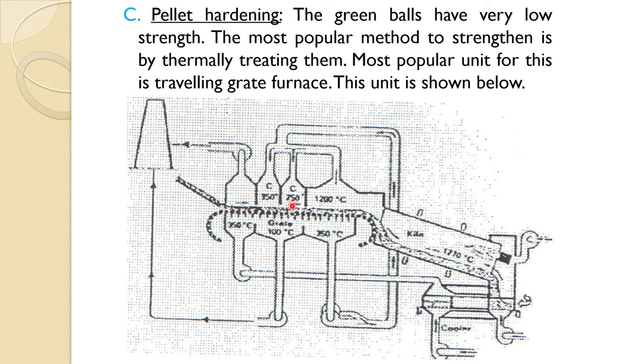Then they come to the next section, which is like a preheating of the pellet. So, the temperature is in the 350 to 750 degrees Celsius zone, and here you are having a downdraft, the way we had in the sintering. So, here suction is applied underneath the moving grate, and this hot air is coming actually after induration, we will come to that section. So, here is a downdraft, before it was an updraft. So, there is a difference. Here the same thing is happening, much more heating, and evaporation and chemically bonded water is going away.